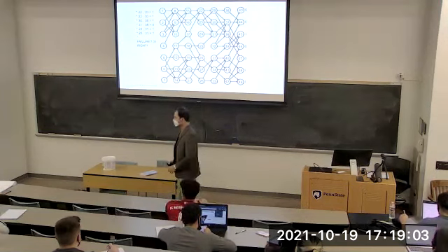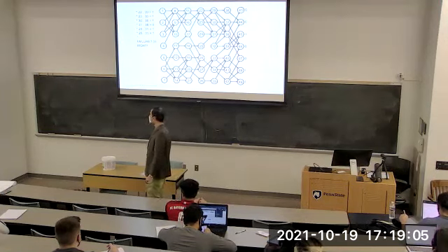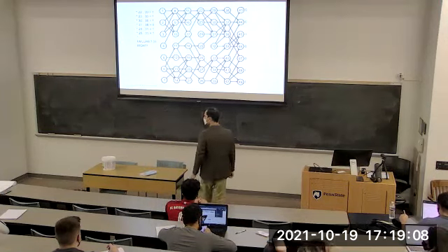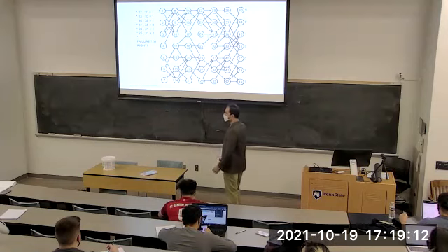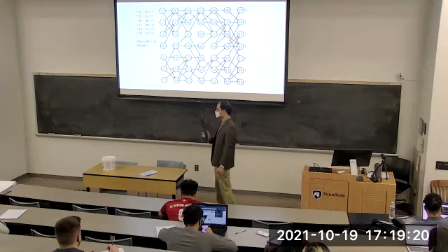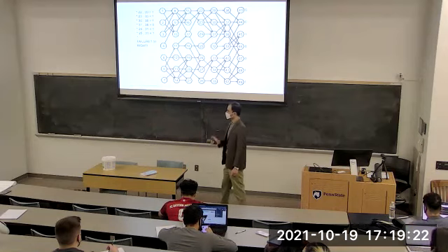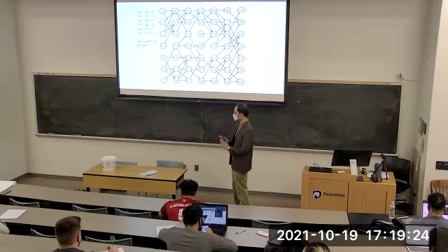Yes? So if you test, let's say, test 44. And although other nodes around it don't work, should you test the nodes around it as well? So if it's 44 that is not working, then you can argue with high likelihood that the assumption of only one faulty component is not working here. There should be more faulty components because you see other zeros here.